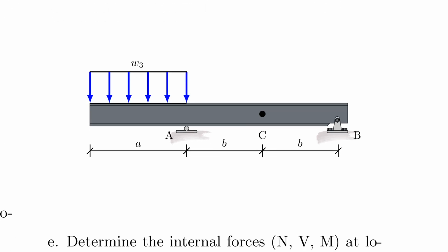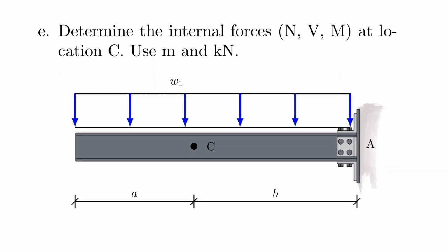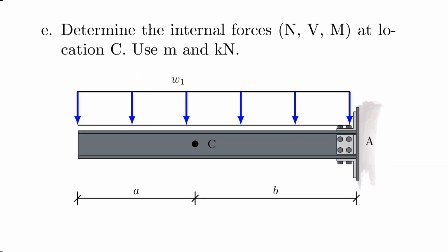So let's take a look at the last two problems. Now it becomes a little bit interesting because this is something we didn't cover in this class, internal forces for a cantilever beam. But to no surprise, it's no different after you found the support reactions. In fact, you may not even sometimes have to find the support reactions for cantilever beams, and this is something that you can learn through application as you solve these problems. Because remember, you have to release either the right side or the left side of the system. And so here one side requires you to find the support reactions first, the other one doesn't.